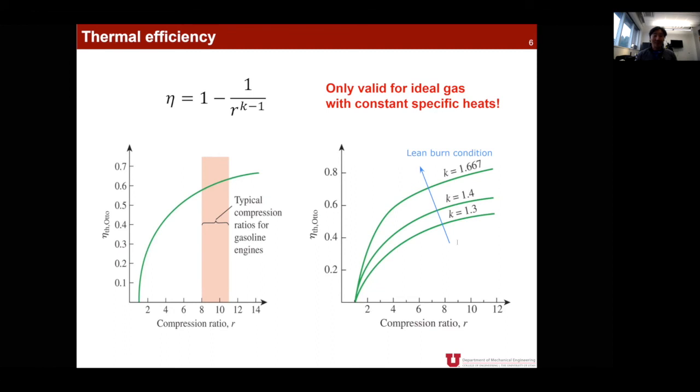What do you think? Was it a big success or a big failure? Now you can clearly answer the question, because you don't see that lean burn engine anymore these days. Yes, that was a big failure. Why? Because yes, you can make your engine very efficient by burning less fuel. That's cool, but at the same time, because you burn less fuel, your power decreases drastically.